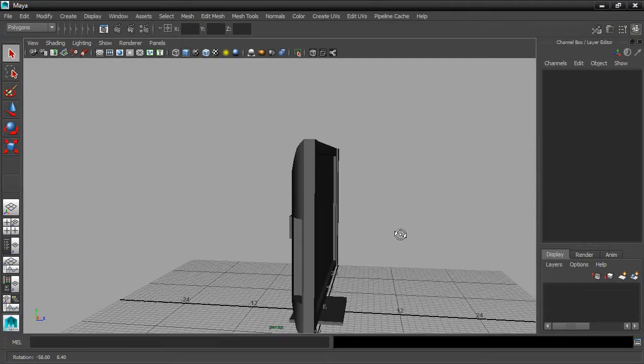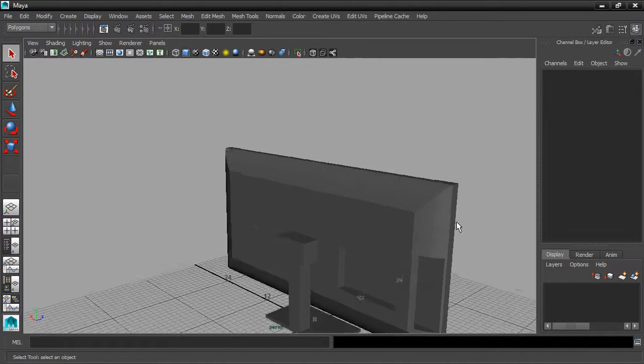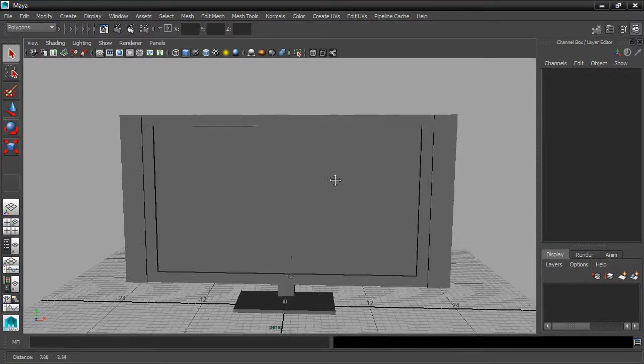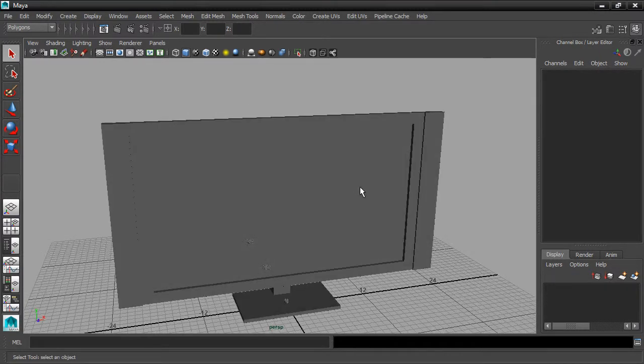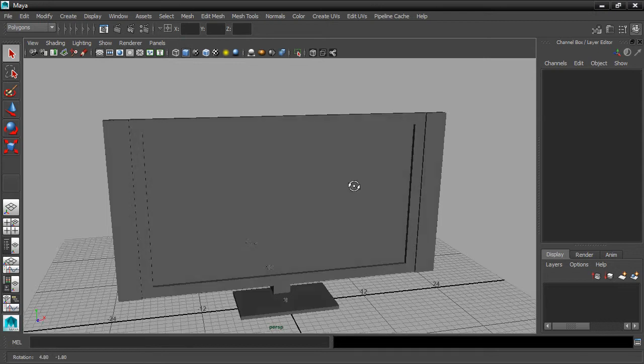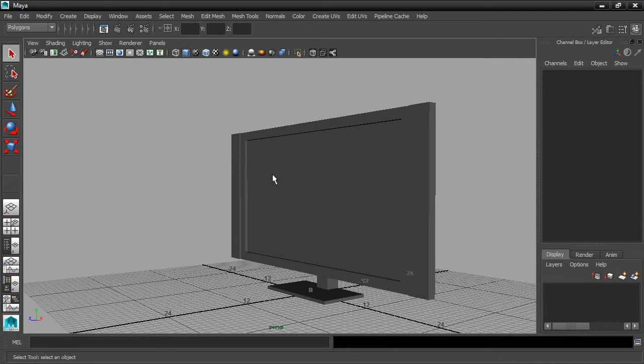When the model is built and all of its edges made hard or soft through vertex normals, then you're ready to assign UVs. The object should have some coordinate values to determine how to apply file maps or other 2D maps onto surfaces. So you can go ahead and add a material at this point, but if your UVs aren't sorted out, then maps may appear in strange places. In this case, I'm going to build the material and then show you the issue of improper UVs so you'll get a clear visual on it.